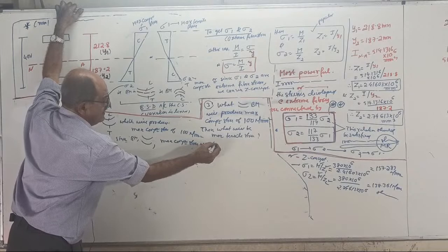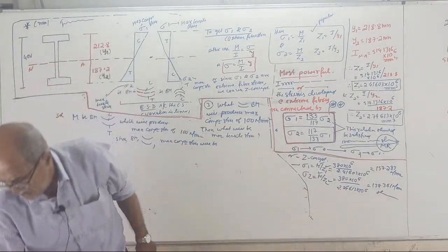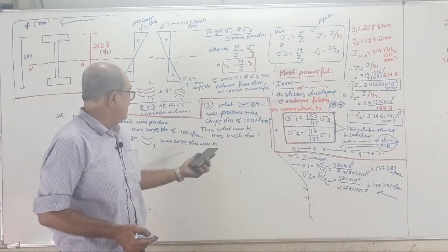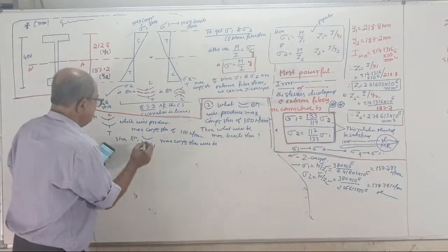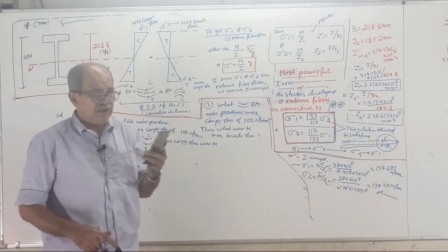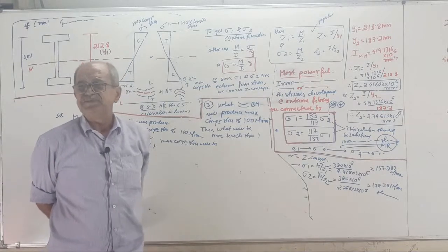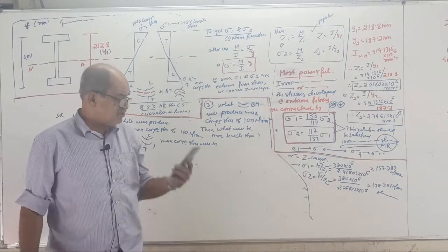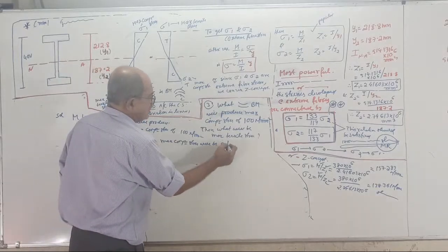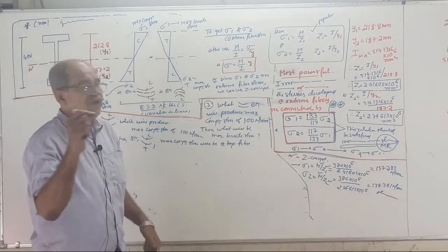will be where? Maximum compressive stress will be where? Since the BM is sagging, maximum compressive stress will be where? Top or bottom? Sigma 2? Then how you told sigma 2 will be at top fiber. Will be at top fiber. Correct?